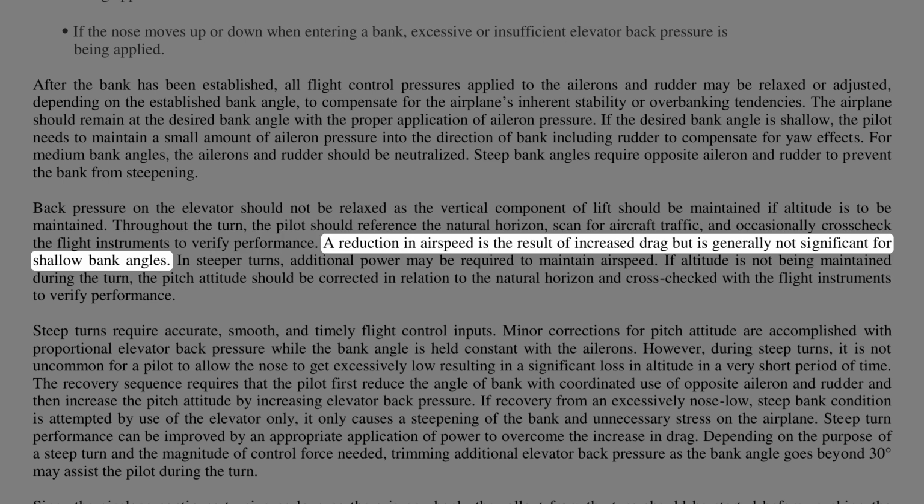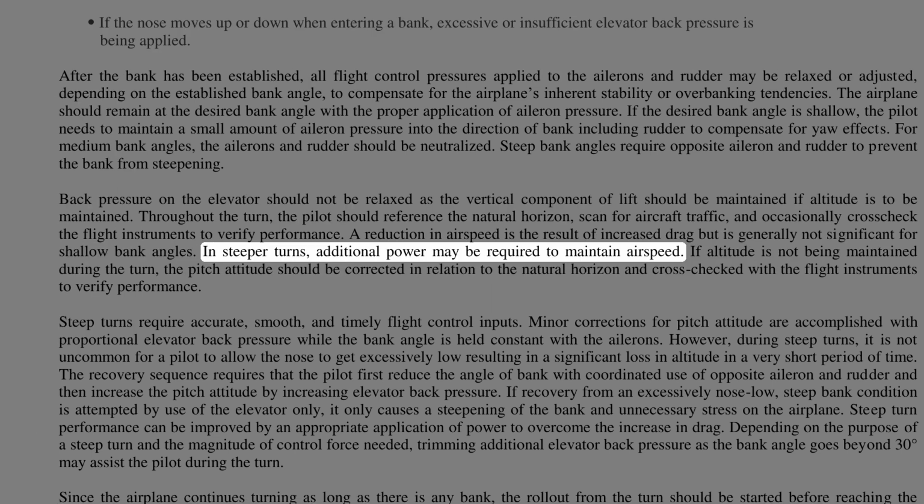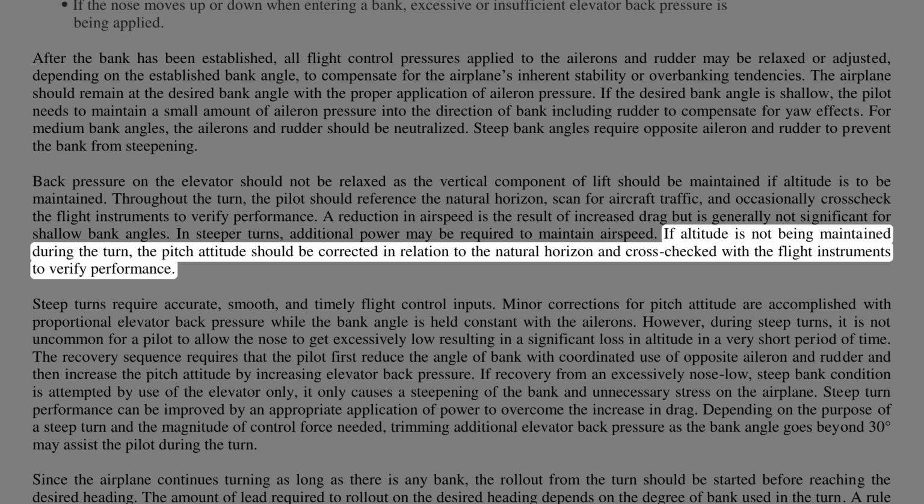A reduction in airspeed is the result of increased drag but is generally not significant for shallow bank angles. In steeper turns, additional power may be required to maintain airspeed. If altitude is not being maintained during the turn, the pitch attitude should be corrected in relation to the natural horizon and cross-checked with the flight instruments to verify performance.